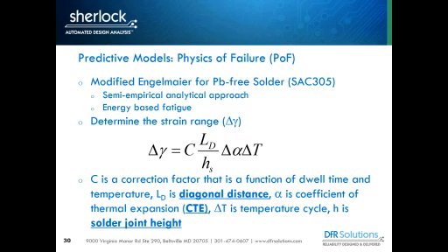People have tried on grain size and growth and stuff like that, but usually when it comes down to it, we're looking at taking fatigue data and using a distance neutral point based type of model and extending that test data to other configurations. If I have a 2512 resistor and I have the fatigue data for that, can I use physics of failure to extrapolate to a different size ceramic resistor? So can I go from a 2512 to a 1206?